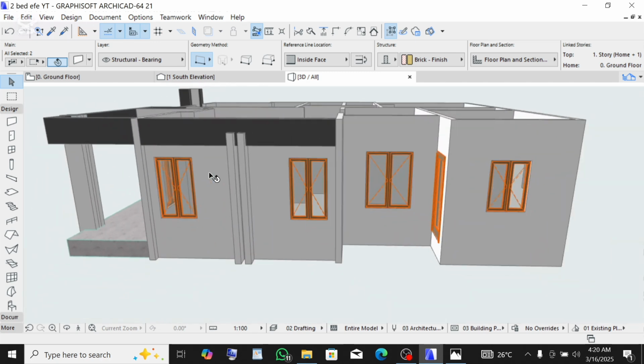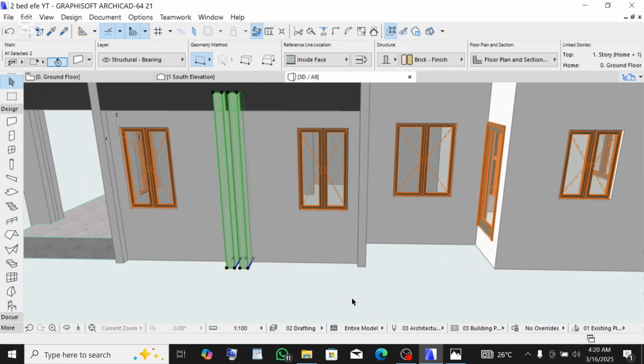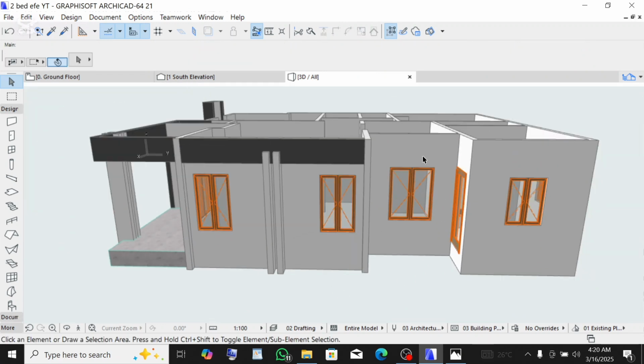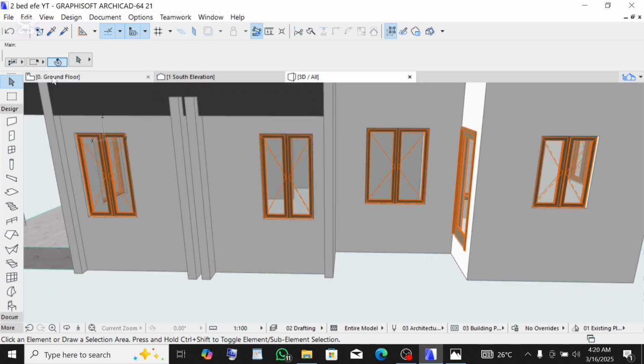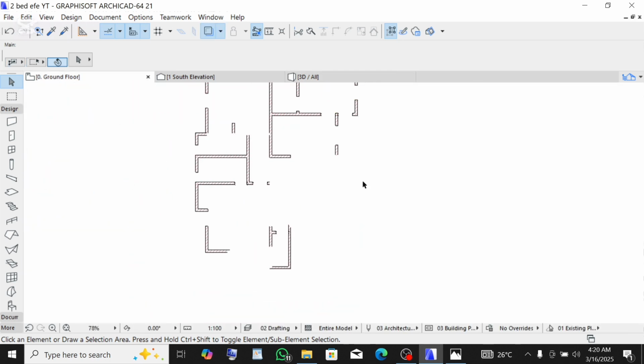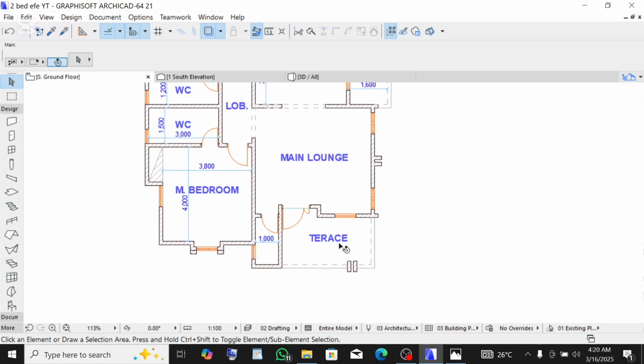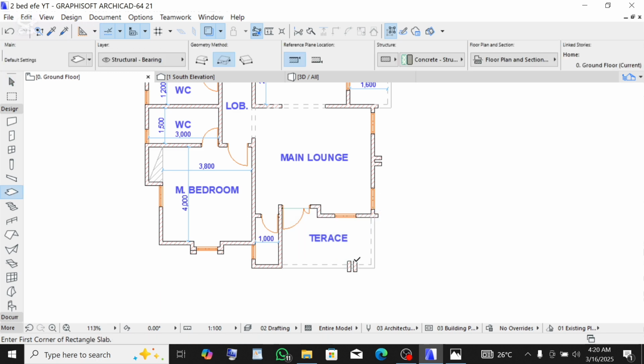Okay. Now the other thing we need to do is to place, for this kitchen terrace, our floor slab and the arc. Let's start by placing our floor slab. So just go to the ground floor. Since we already have a floor slab here, let's use the same floor slab. Press Alt on your keyboard, hold it, then click on this floor slab, then go here.